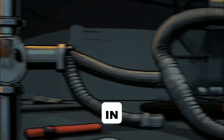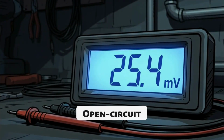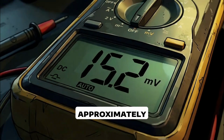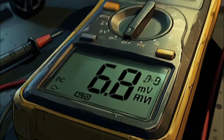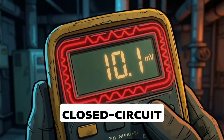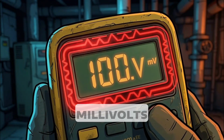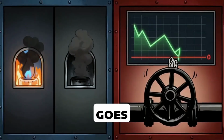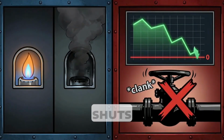Common readings shown in training material are: open circuit test approximately 20 to 30 millivolts. Closed circuit test approximately 10 to 20 millivolts. Minimum acceptable closed circuit reading approximately 10 millivolts. Normal dropout may occur around 2 to 4 millivolts. If the pilot goes out, voltage drops and gas shuts off.